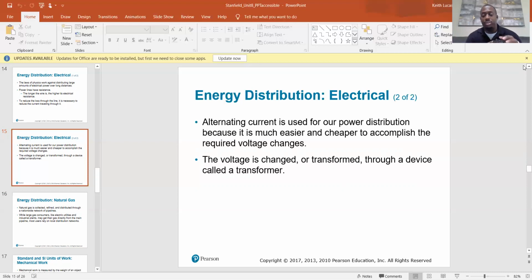At your condenser, you'll have a contactor like this one. You have your high voltage traveling through here. You have 240 volts resting here, waiting to pass through and power up your compressor and condenser fan. But this 240 volts can't pass until this is closed. When it's open, the circuit is broken.